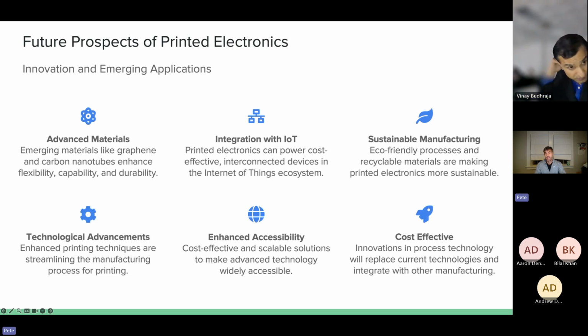The inkjets are more non-contact because they don't actually have a meniscus of fluid that touches the substrate. They shoot it out, so they can be tens of microns above the surface, where we have to be a lot closer. Our dispenser does not actually touch the surface, but the meniscus of the fluid does.